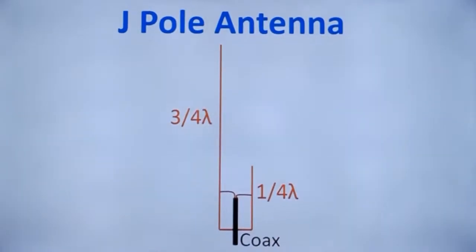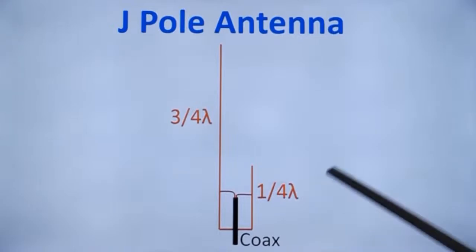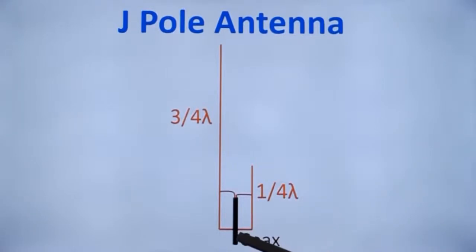If you are using a galvanized iron pipe, as is usual among us radio amateurs, then a section of non-conducting material like a wood piece or PVC pipe has to be attached below the antenna, between the antenna and the mast. And the length of that should be at least about 3 times this separation between the two elements. And there should not be any other conducting material near this, like a window grill or another mast, very near to this antenna for best performance.